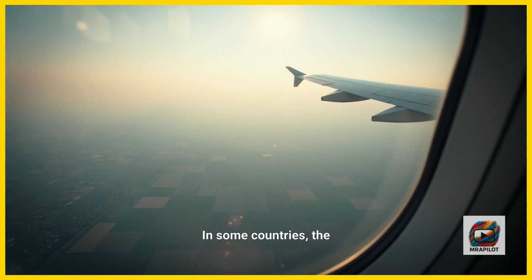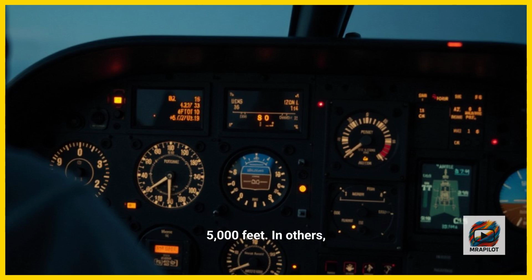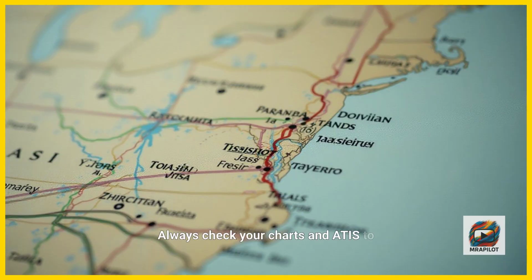In some countries, the transition altitude is fixed, often around 5,000 feet. In others, it varies by airport and weather conditions. Always check your charts and ATIS to know the correct transition point and avoid altitude mismatches.